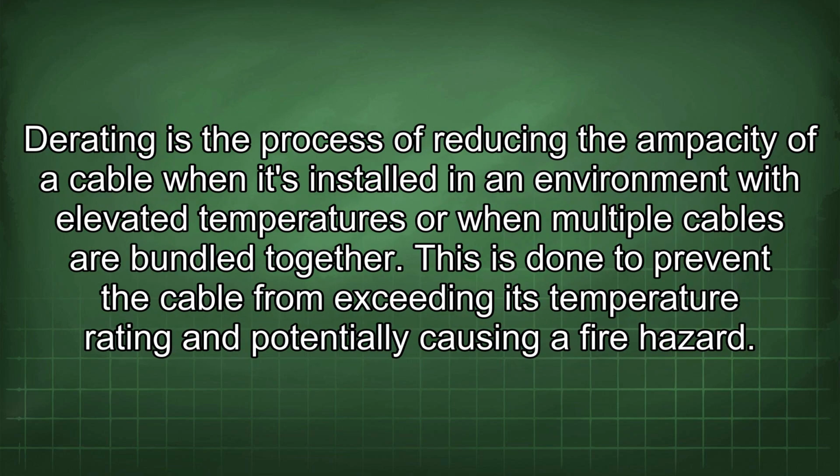Derating is the process of reducing the ampacity of a cable when it's installed in an environment with elevated temperatures or when multiple cables are bundled together. This is done to prevent the cable from exceeding its temperature rating and potentially causing a fire hazard.